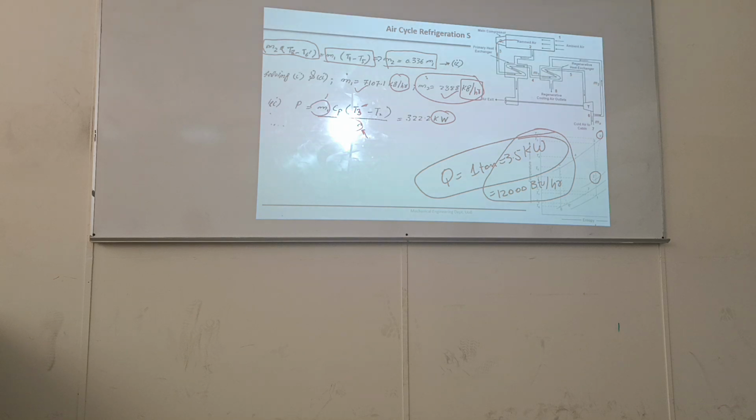And there is also some more important information. Meter cubes per hour is also given. Meter cubes per hour is the flow rate at the inlet of the compressor, how much volume the compressor is dealing with at the suction side. That is also written here: 125 meter cubes per hour. The rest is electrical data, this much kVA and so on, power of motor.